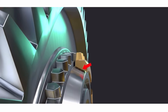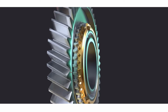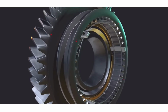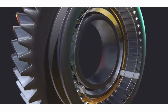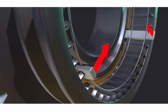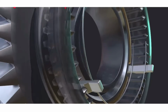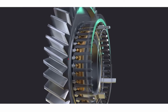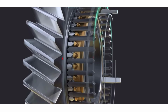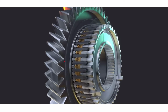This system flushes away the double declutching problem and makes the drive less noisy, as the spur gears of the sliding mesh are replaced with helical or bevel gears, but the shifting of gear is still not smooth, and also there is a lot of wear and tear of the dog clutches due to the different rotational speeds of the shafts while meshing, which leads to high maintenance. Note: it came with a 4 or 5-speed, 1 reverse manual shift configuration.